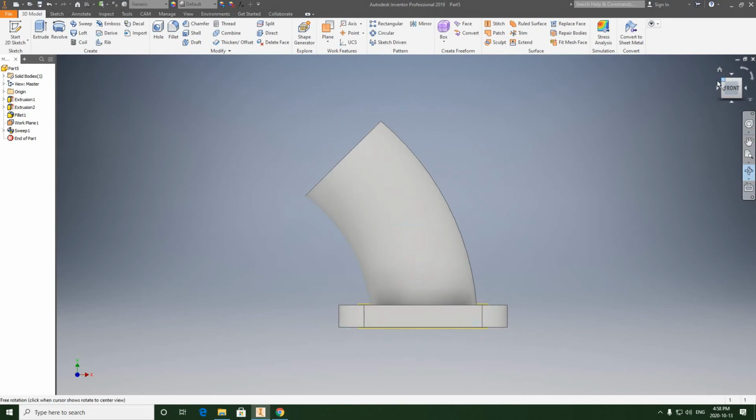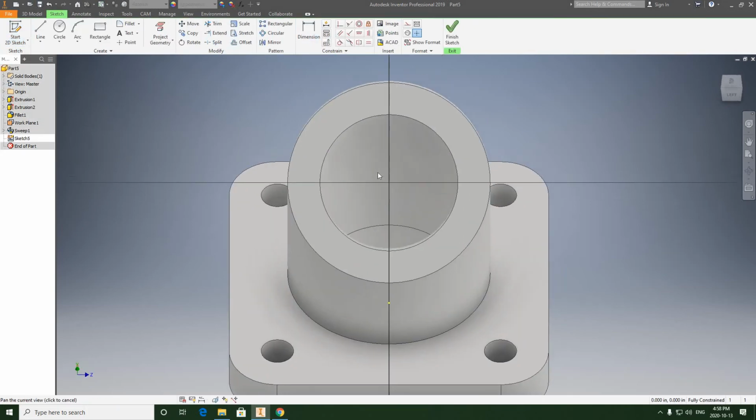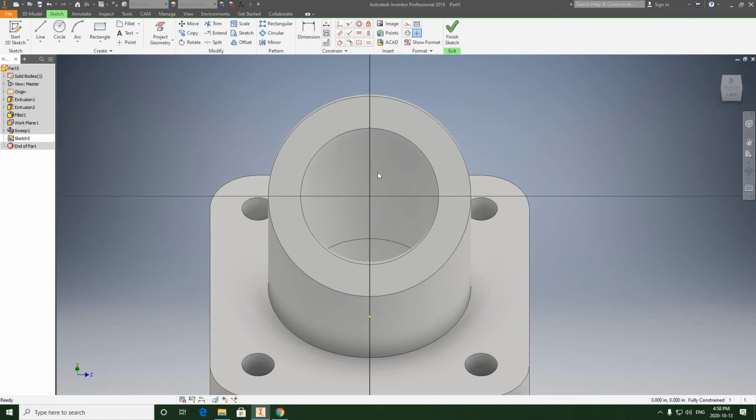Now at this stage, we can create the bolted flange that sits at the top, that has the slots in it. So we're going to start a 2D sketch on this face. And we're going to draw a circle. We're going to pick up x, y, 0, 0, and create another hole. And this is the core value again, 1.62.